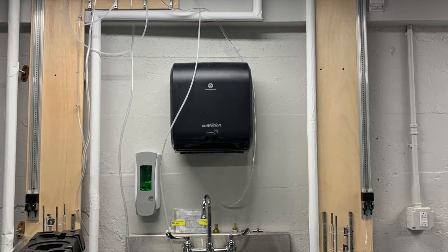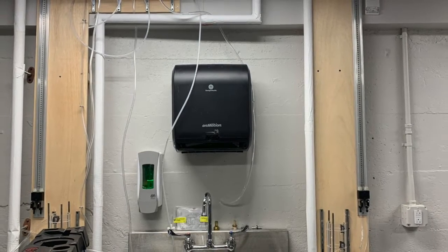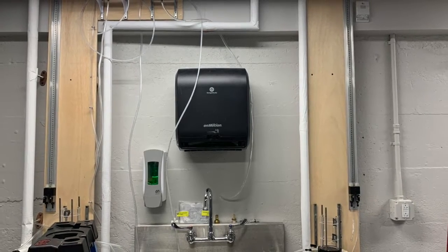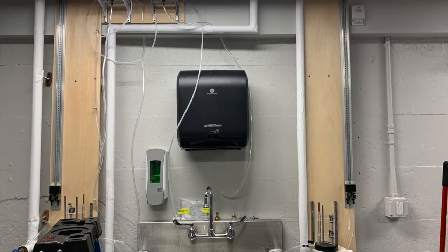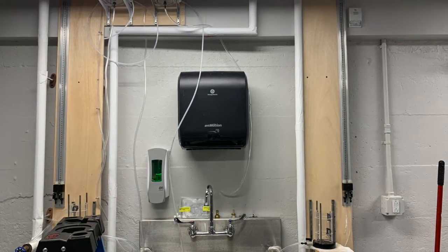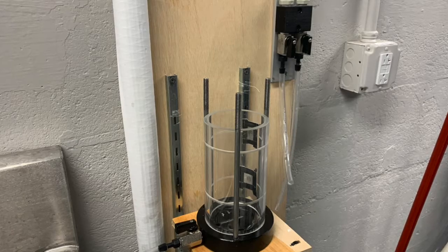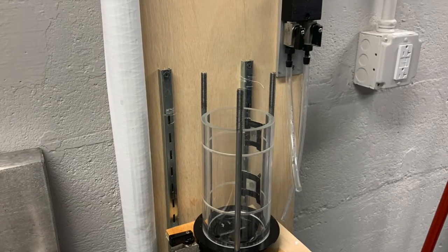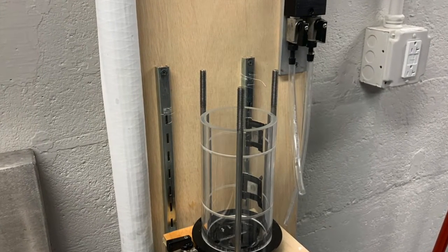The experiment that we will be performing is a soil permeability test using a constant head tank. The purpose of this lab is to measure the permeability constant for various materials. Permeability is a very important quality to see how water moves through certain materials, and based on this, it can be used to determine which material is needed for the engineering design.